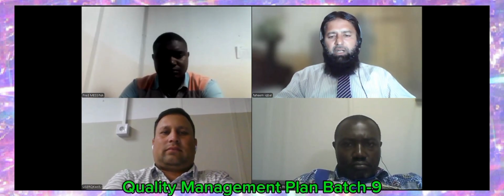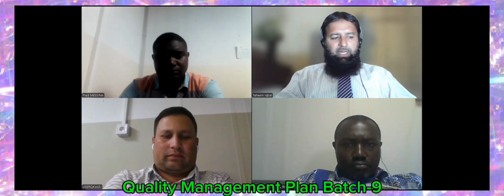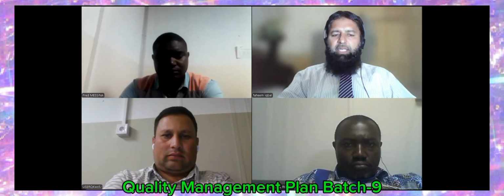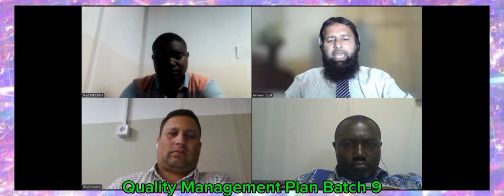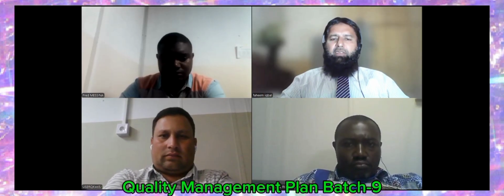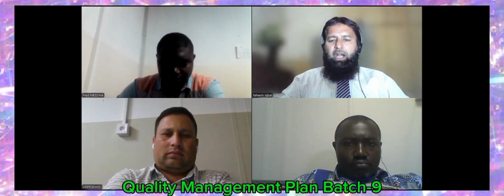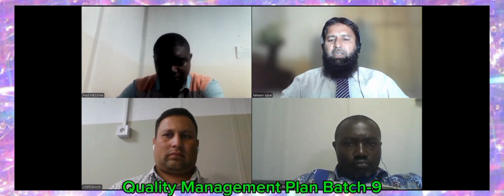At the Nachtigal project, ATB agreed with EDF regarding the welder qualification test. They use ISO 9606 for the welder qualification test. There are three standards for welder qualification test. The first one is ASME Section 9, the second is the European standard, EN 287, and the third one is ISO 9606. And ATB agreed with the customer, with the sponsor, with EDF, on 9606. That was an ISO standard,